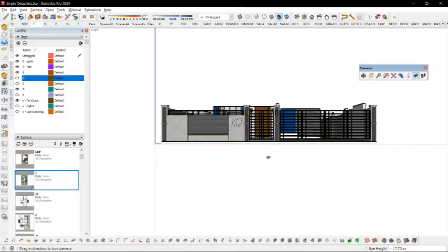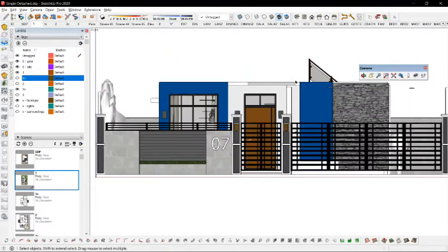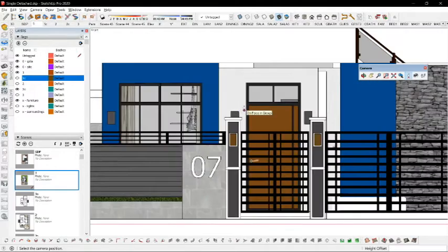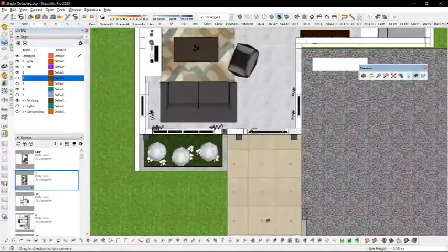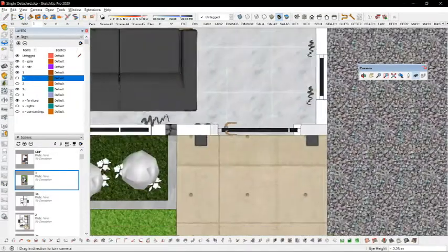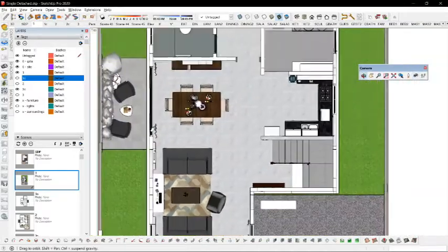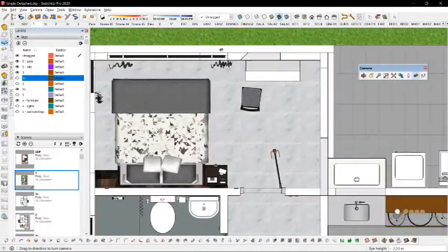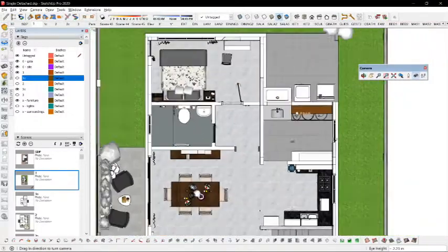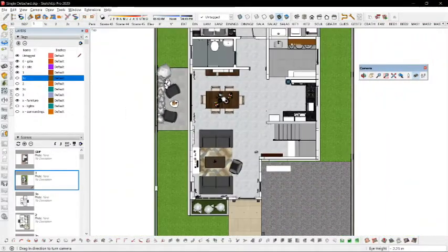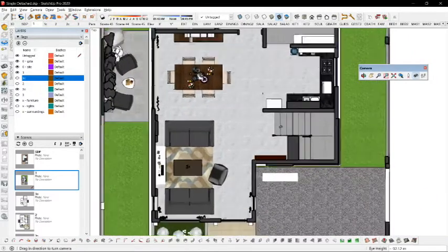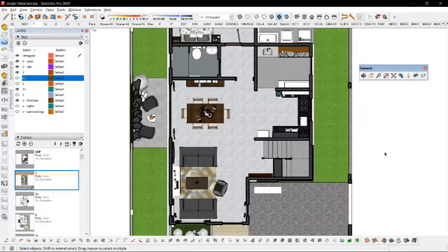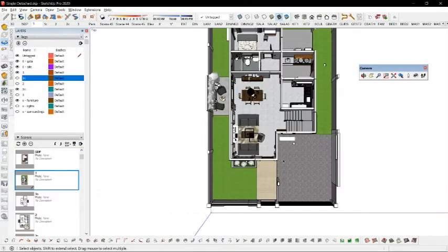Okay, again, front view, Shift F. I want to start the camera plane from here below the door jamb. Let it face downward. There, it creates a kind of cut, but without the section plane or the section cut outline. Compare that to using a section cut, which actually looks like this, where you can change the color of the section fill.